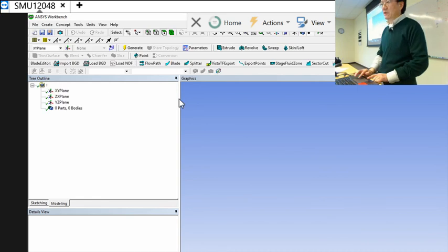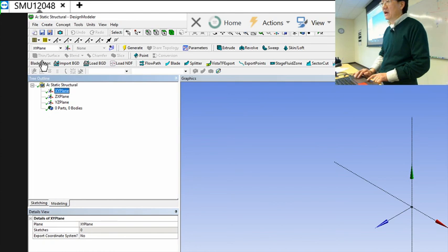Inside the DM, the Design Modeler, you click the XY plane and make it 2D. Use Look At: right mouse click, and you will see Look At. You also can use the 3D orbiting. Either way should be fine. Once you have that, we can start the sketching.